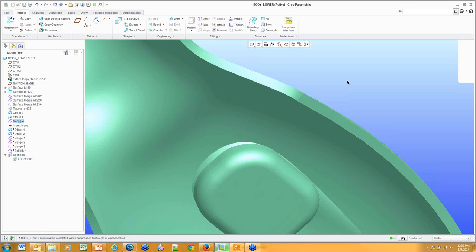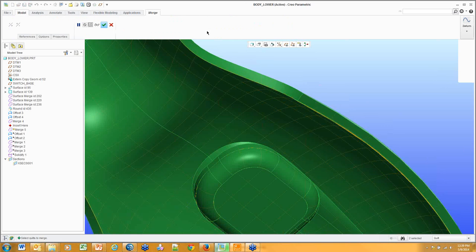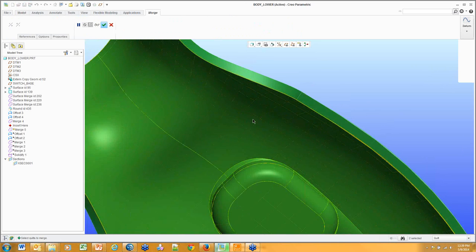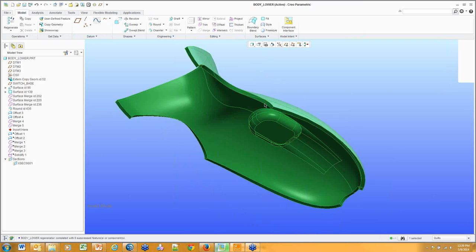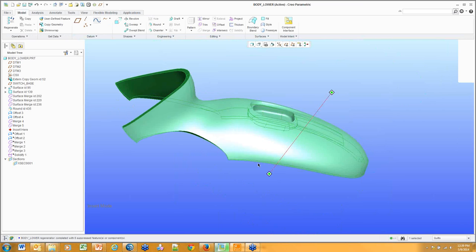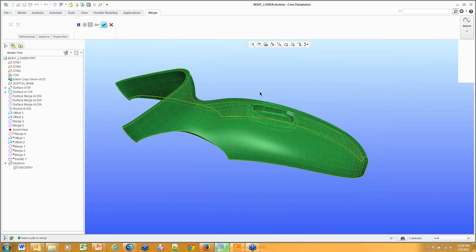Now we want to attach that quilt to the edge. So again, pick the quilt, press Control on that quilt, and back to Merge. Okay, again, these are working properly by default. Complete that. And lastly, this quilt, press Control on the original quilt, merge a third time.